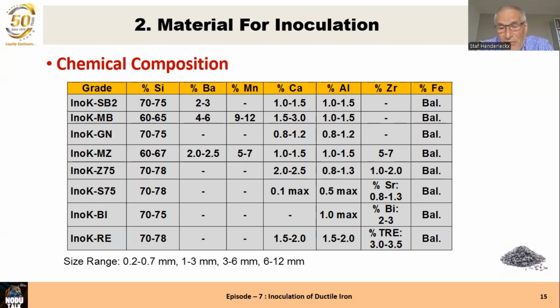Aluminium, you have from 0.5%, nearly nothing, to 2%. Aluminium is added, but pay attention, because you can risk pinholes, especially in the monsoon season, when everything is high humidity. Aluminium is a little bit dangerous. Zirconium is an element that can be used mainly for thin castings, but be aware that zirconium will also react with aluminium. So there will be an interaction between zirconium and aluminium.